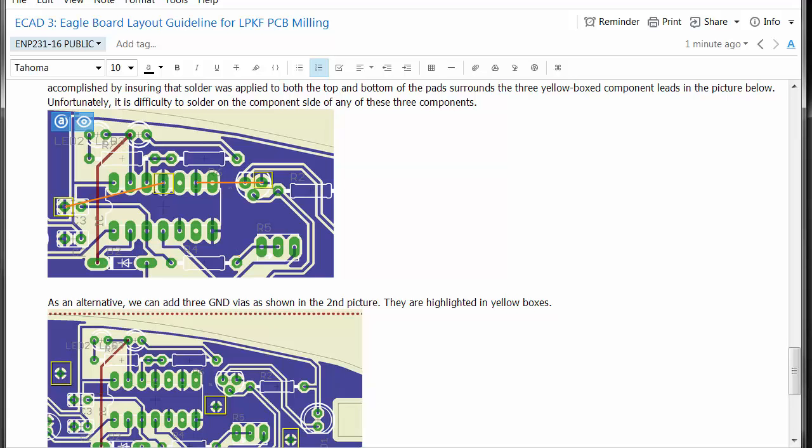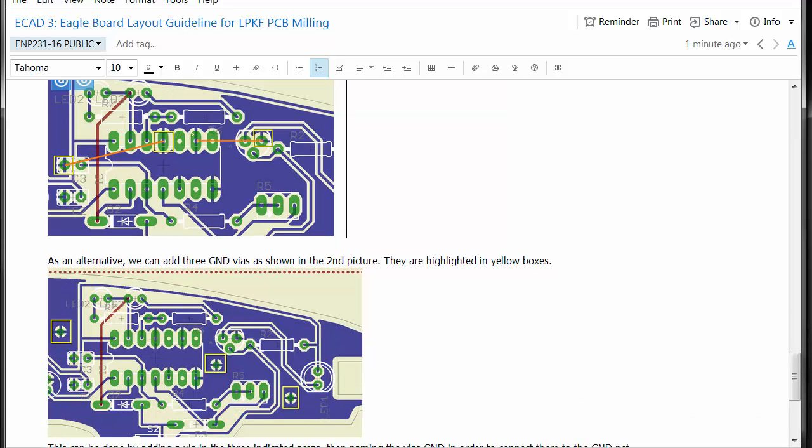That's what the orphan checkbox does. It allows it to fill areas that it can't be connected even though you want them to be electrically connected. So it's telling me that these are not connected. What I can do is provide a ground fill on the top, and that ground fill on the top can help connect these three grounded areas. Specifically, those connections can happen through this pin, and this pin, or this one.